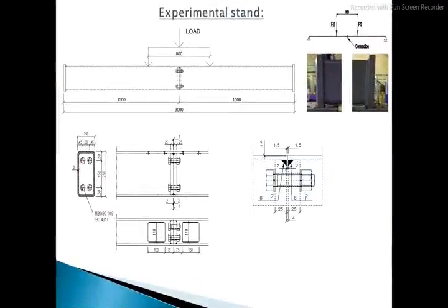For that purpose, an experimental stand was set up to determine the response of an inline connection of two RHS profiles. Each element assembly consists of the RHS 250 x 150 x 8 profile with a support end plate and the connection end plate welded inside the profile. Each element assembly had a cut 150 by 110 as a hand hole for access to the M20 grade 10.9 bolted connection, which reduces the capacity of the structural element. A gap of 4 mm exists between the two connection end plates to allow direct contact between the RHS profiles, such that the continuity aspect of the element is provided.